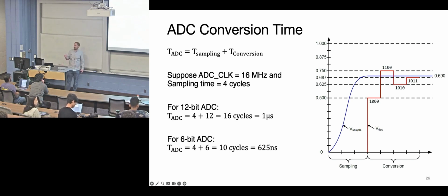Because I think the challenge is there's no inherent advantage of stopping early, because then you take another sample, and then your sampling time is all skewed, right? When you take a sample, it's dependent on the analog voltage that just came in. And so now your time base is varying. Does that make sense? So it just won't change the value. It'll stay constant. It'll just wait till the end, and then it'll say, I've converged, take the value from the ADC, the digital value, put it in the output register, and start again if you've told it to do that.